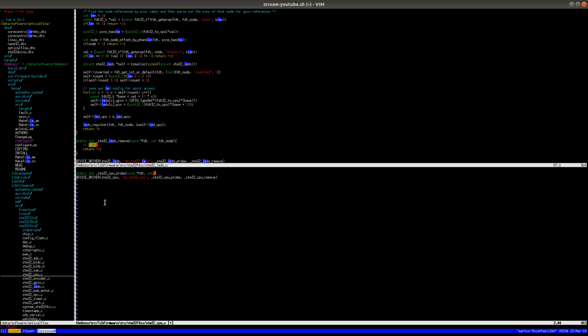I have been refactoring a lot of the build process that is responsible for compiling in the device drivers, because I wanted to make sure that stuff that is not used doesn't get included. It gets a little bit tricky there though, because when you have things that automatically initialize like this, you get the problem of including too much code. If you just compile in all of the drivers, you end up with drivers that you're not actually using, so the firmware size can increase.